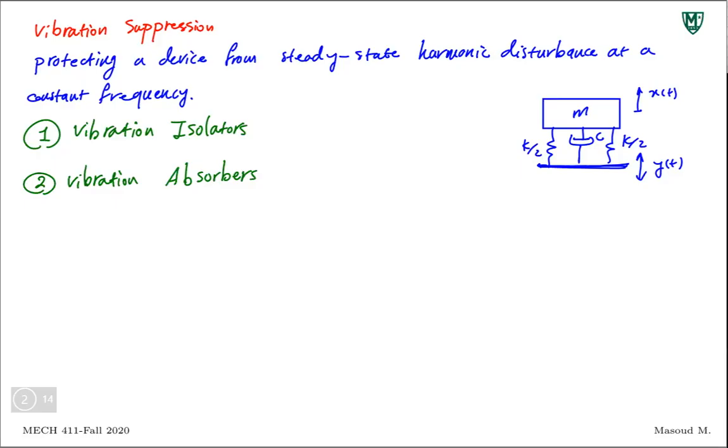Now, in this case, we have, let's say, a spring mass system. Right? Vibration absorbers that we talk about, at least in the scope of this course, we're gonna stick to just the type that has springs. Now, there is a more advanced version that has both the spring and dampers, right? And there is a different way to design those absorbers. But we're just gonna stay with the type of vibration absorber that only has the springs. So our system is a mass spring system. Right? Some forces applied to it. Remember, base excitation of vibration isolators or vibration isolation. The case for that, the base was moving with some applied displacement, right? Some imposed displacement.